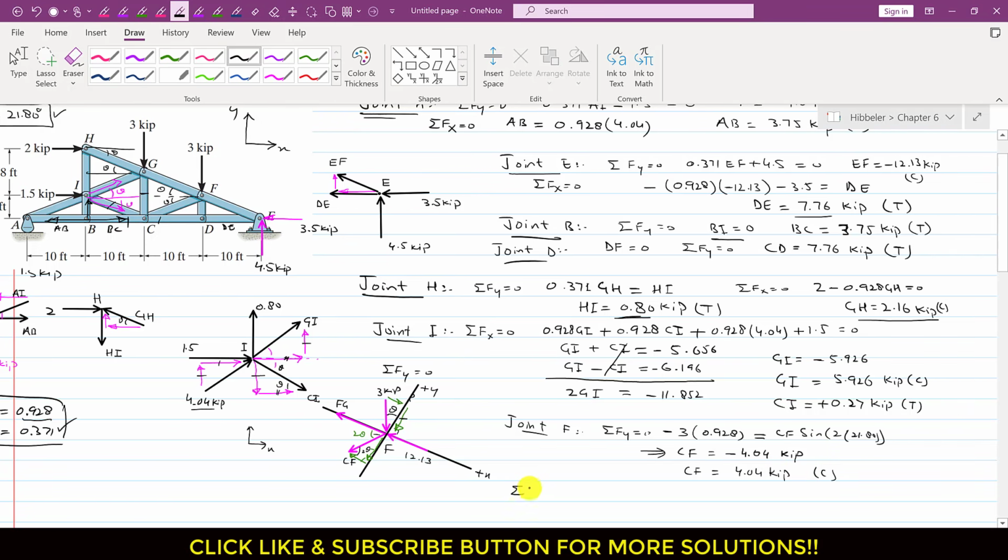Now if we apply the summation of forces along x equals 0, this GF force is acting in the negative x direction, so I will write minus GF. This component is acting in the positive x direction and it is the sine component, and the sine value is 0.371, so I will write plus 0.371 into 3. Similarly, this component is also acting in the negative x direction, so I will write minus, and this is the cos component of CF.